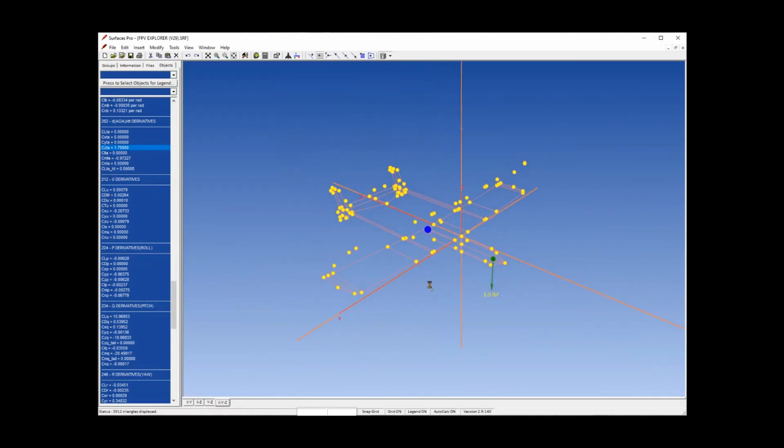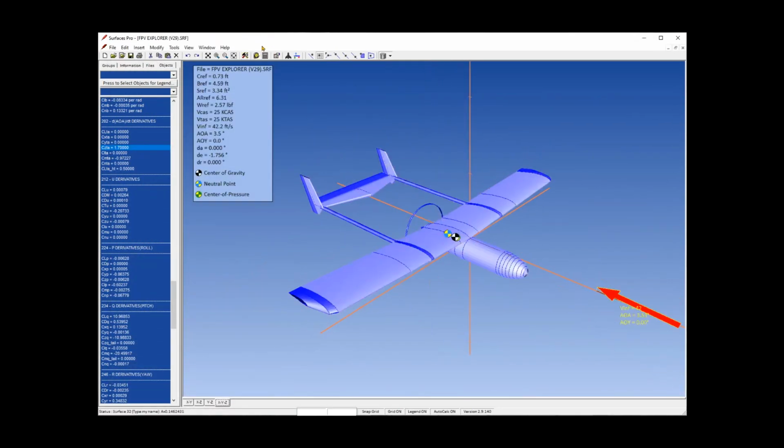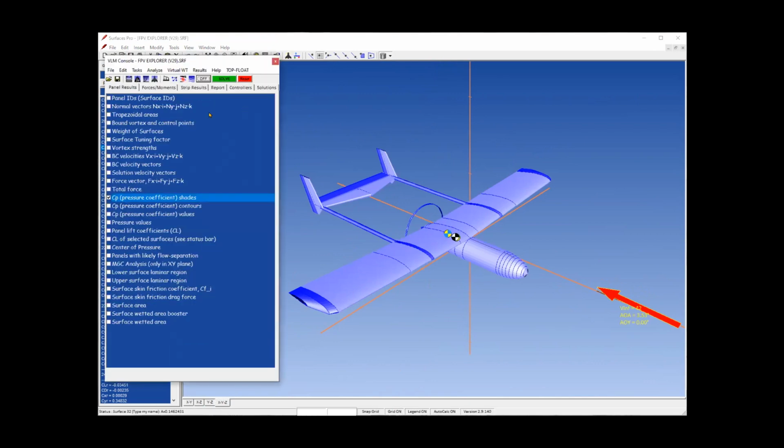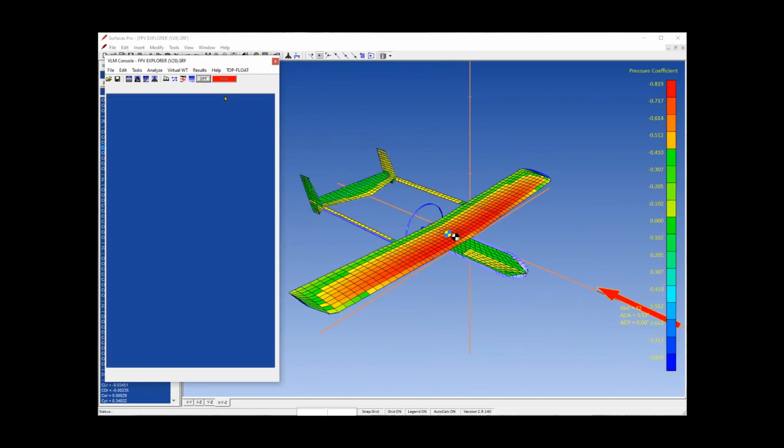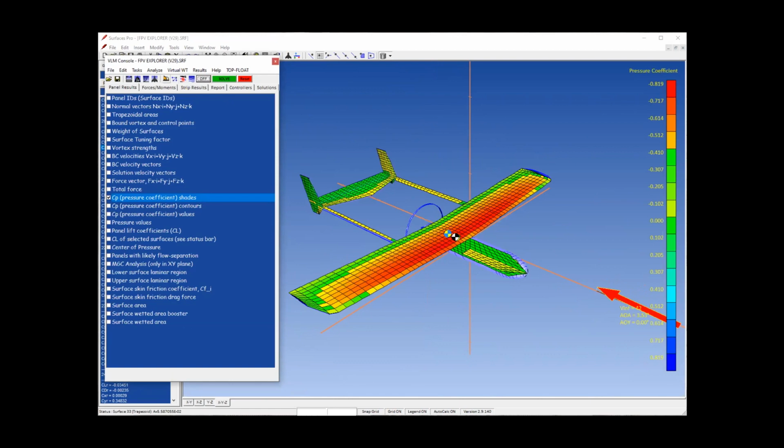Two additional matrix solvers are offered, a Gauss-Seidel and a lower-upper decomposition solver. The former offers significant speed improvements, between 4 to 8 times faster. Unfortunately, it is restricted by the properties of the aerodynamic influence coefficient matrix that depends on how the model is made. Sometimes this renders the Gauss-Seidel algorithm unable to converge to a solution, but when it does, well, it makes a huge difference.